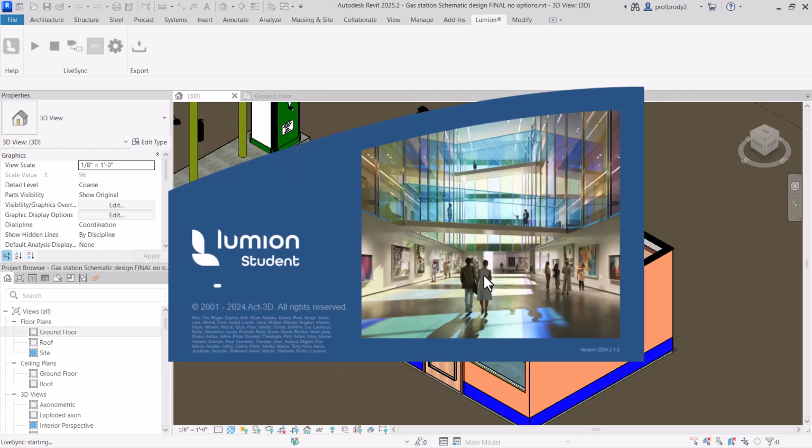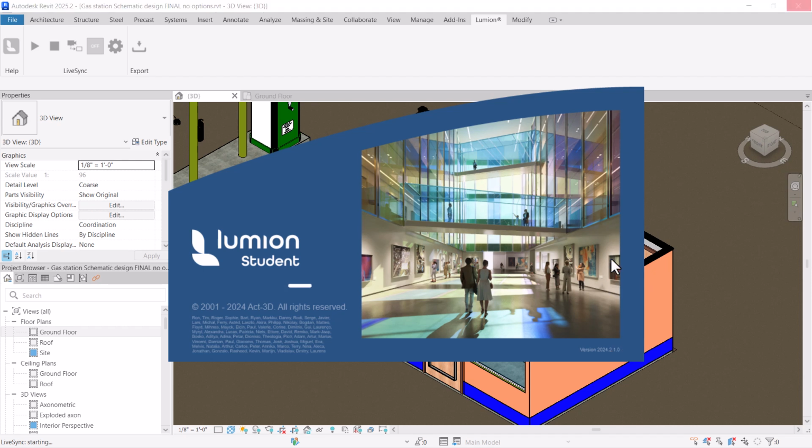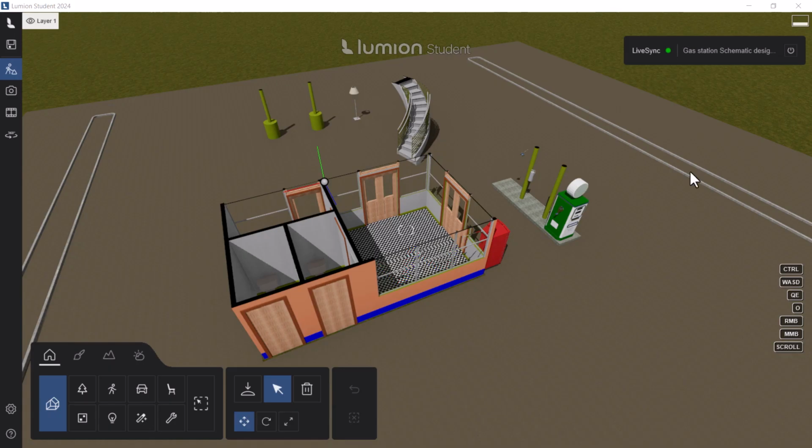And launching Lumion from this view will retain that characteristic. So now when Lumion starts, you'll see that section box. And you can see the section box has cropped away the model, and anything that's cut through gets that black color defined by the material in poche in Revit. It's kind of a weird way that it works, Lumion mostly respects materials, except in this one instance.